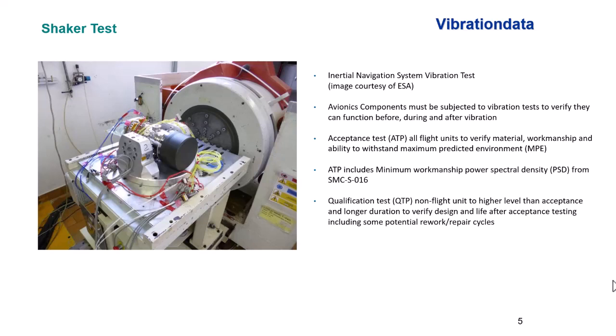And also the QTP test duration will be longer than the ATP duration. Now we say that that is to verify the design of the component and to demonstrate that the acceptance tested flight unit will have remaining life after it successfully completes its acceptance test.